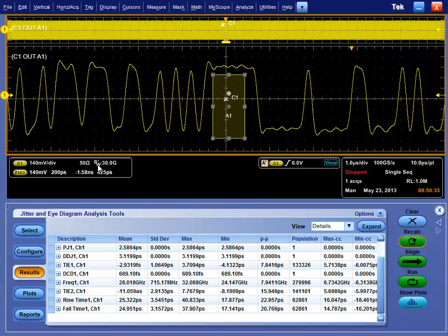What that means is with this probe, I've got 30 gigahertz out at the probe tip, and all of my measurement reference planes have now moved to the end of this probe where I'm connected up to my device under test. So I do not have to de-embed or simulate anything, because this waveform is what is coming out of my device under test.